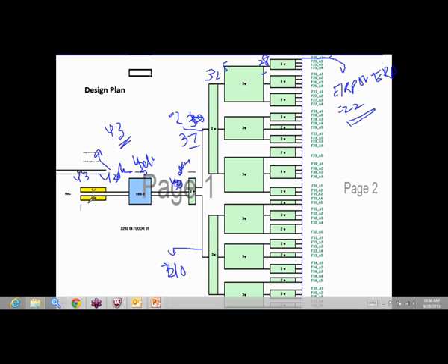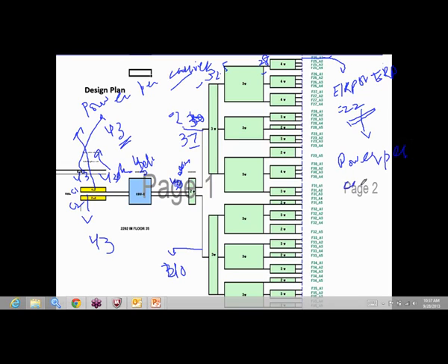So this is 43 dBm and this is 43 dBm. So in iBwave, these are two carriers, right? Carrier 1, C1, C2. But in iBwave, this is called power per carrier. Okay, so this is power per carrier basically. Since we started our calculation on the basis of power per carrier, this ERP will be called power per carrier ERP.